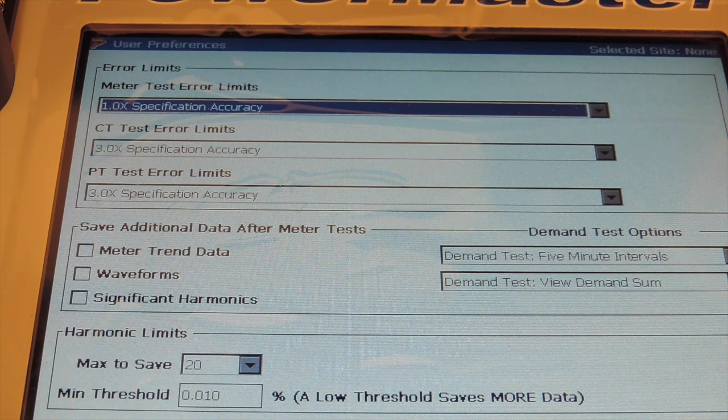And the reason for this is CTs are accurate at their rated load, at their burden level, with a sinusoidal waveform, and their correct temperature. In the fields, you have burden added into the system, you have harmonics, you have switching loads, you have temperature, all that play effect in the accuracy of a CT.